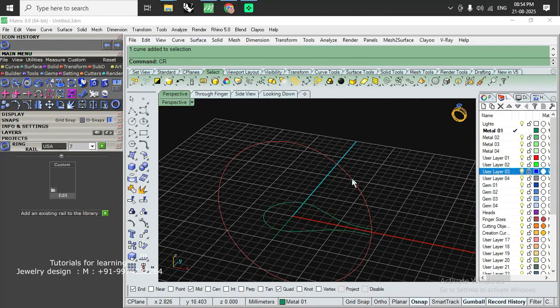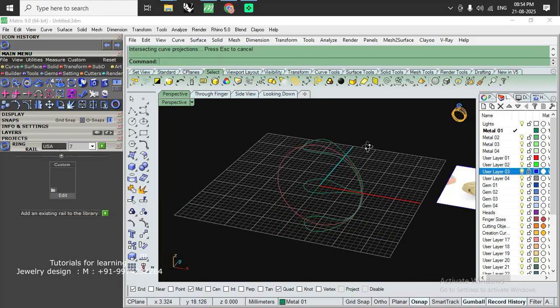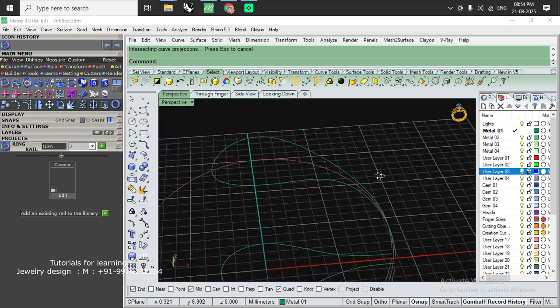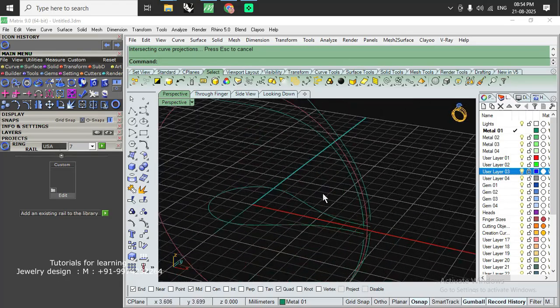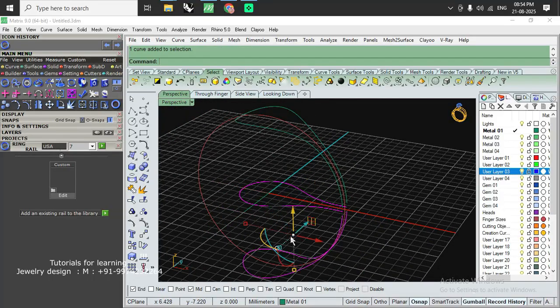So let's make it curve from two views. So here is the option. Select this circle, and select this, sorry, let's turn on the option, select this line and select the circle, ring rail. Curve from two views. Select first curve, second curve. Okay, so we will have this resultant curve. So now if we don't require these curves, select them and move them to another layer. Don't delete the objects, and type in rename here, extra objects.